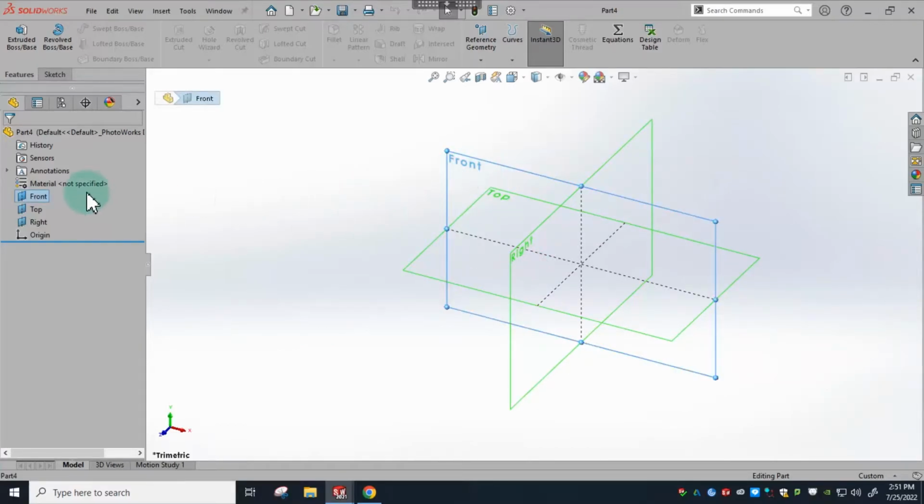If I click one, it corresponds to them over here. You can think of these as your datum planes. If you remember a datum reference frame, it's three mutually perpendicular planes. You're essentially building the part in SolidWorks on your datum reference frame. So when we go to make drawings, it should all tie in together.